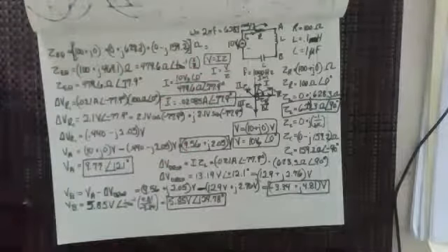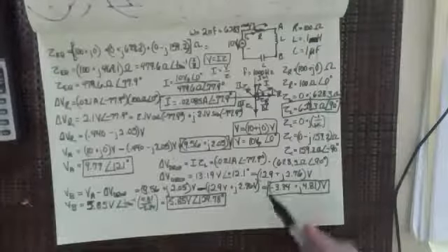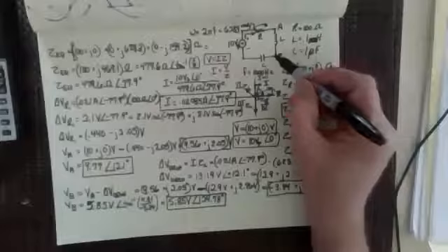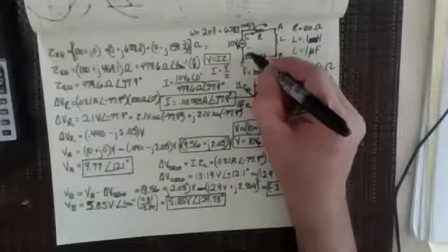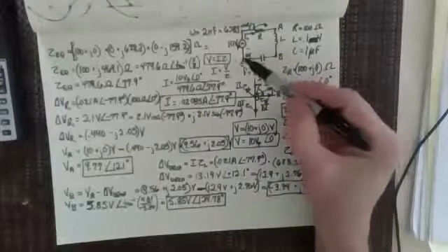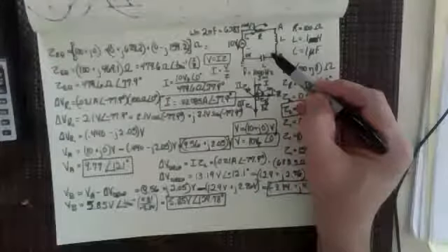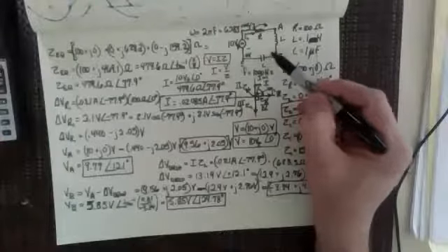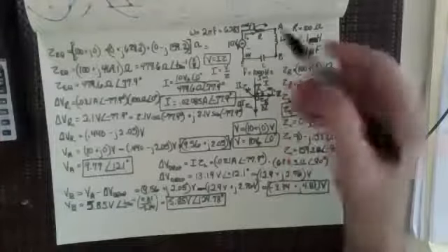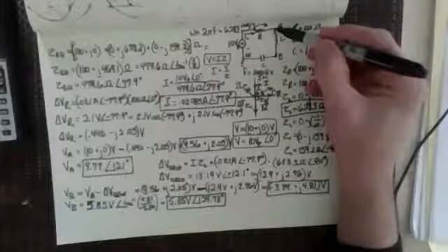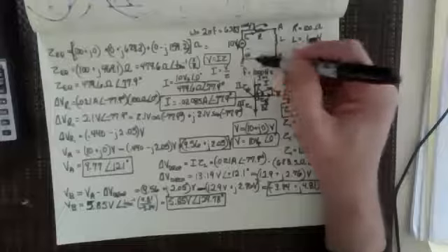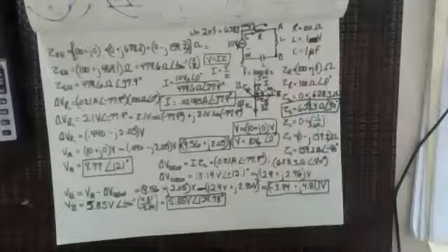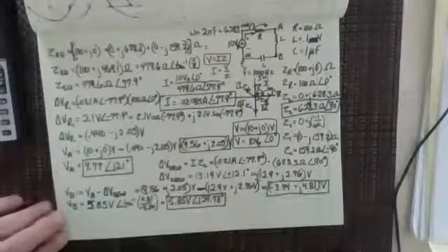Now, the last thing that I wanted to do, and I'm probably taking way too much time to do this, is I just want to make sure that that's right for B. Because, you know, this being 0 volts right there, I should be able to just add that impedance times the current going over C, and I should get the same voltage, right? I've come to this voltage by going from A down to B. Now I can come from this voltage here at 0 and add the voltage in there. Let's see if that works.